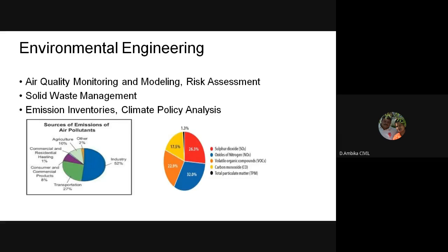So what we did, we have taken the project to analyze the particulate matter released from the tannery industry especially. We have a lot of industries in SIPCOT, but we focus on the tannery industry, which emits more particulate matter. So we have used a respirable dust sampler and the fine particulate sampler, which reads accurately the particulate matter of 2.5 microns and 10 microns.